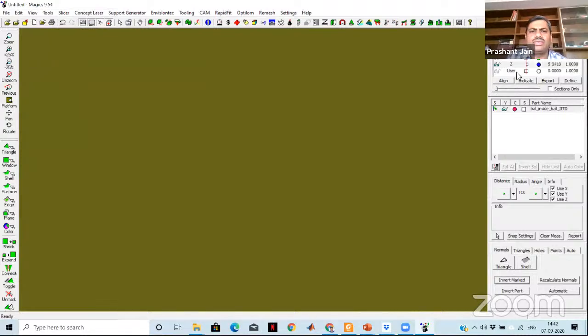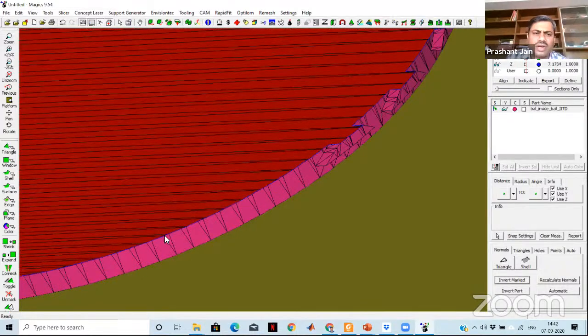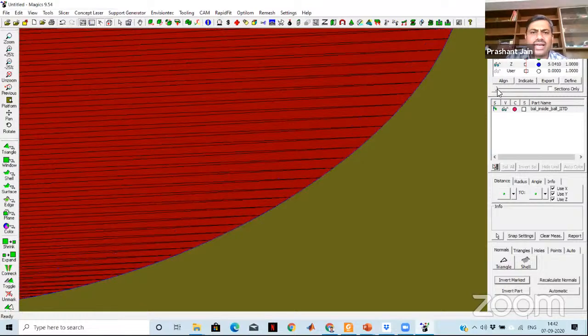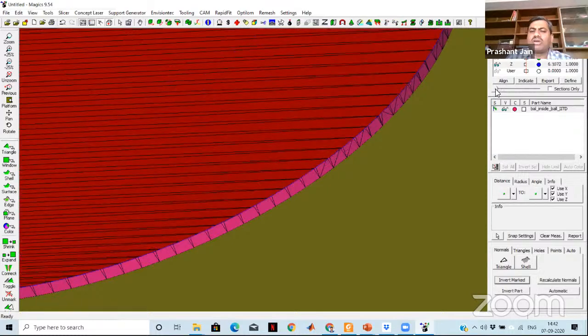Look at this. This type of cut would be there. You can see the two triangles there, and this blue color plane will go and collect the two intersection points. And when we join them in a logical sequence, we will have this entire contour information, right? So that is the purpose of the STL file, tessellation, and getting the contour information.